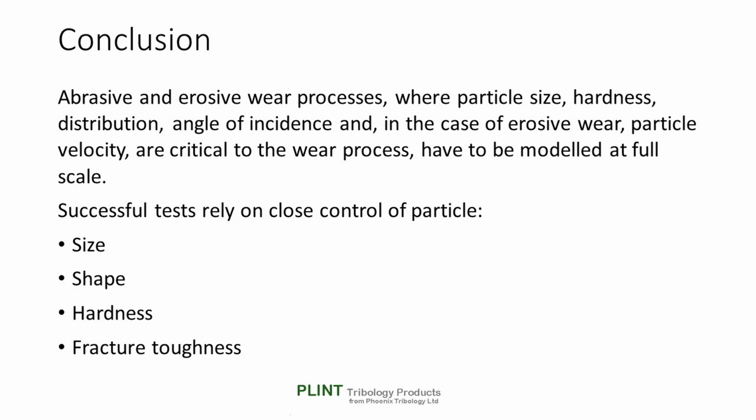To conclude, successful tests rely on close control of size, shape, hardness and fracture toughness of the abrasive or erosive particles, and this can only be achieved by careful sourcing and grading. For further reading, the following slides have a selection of useful references.